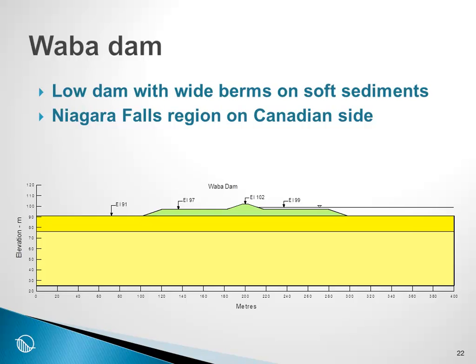And as you can see by the side berms and the very flat slopes, this dam had a very high factor of safety under static conditions because of its very weak foundation. The foundation soils are clay soils, weak clay foundation soils. And the question was what would happen to this dam during an earthquake analysis.